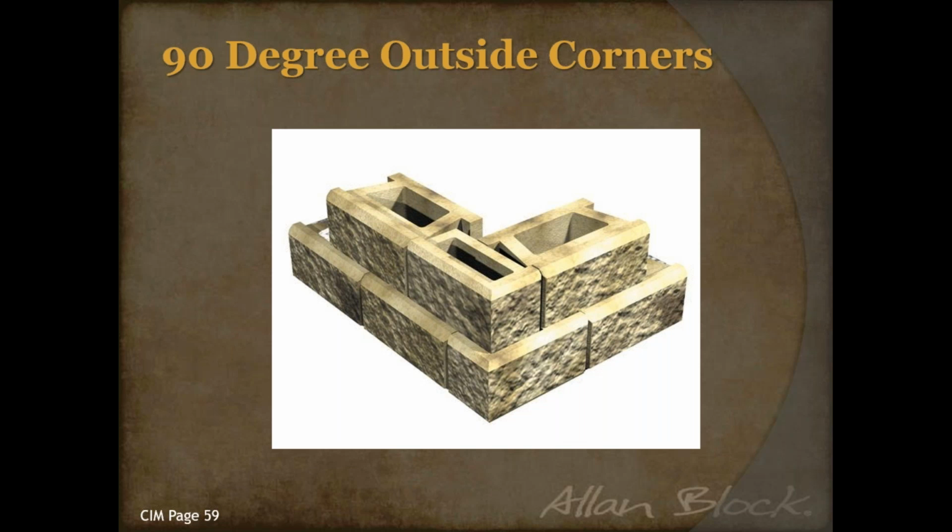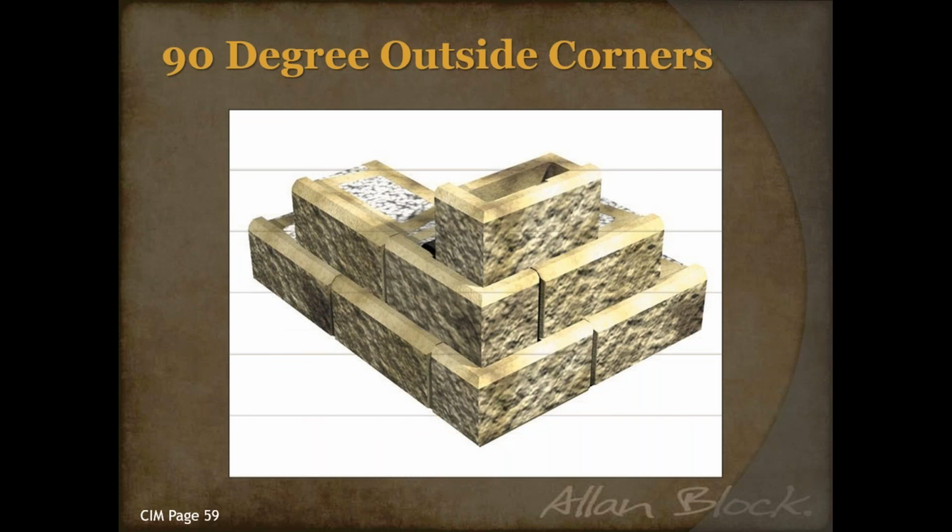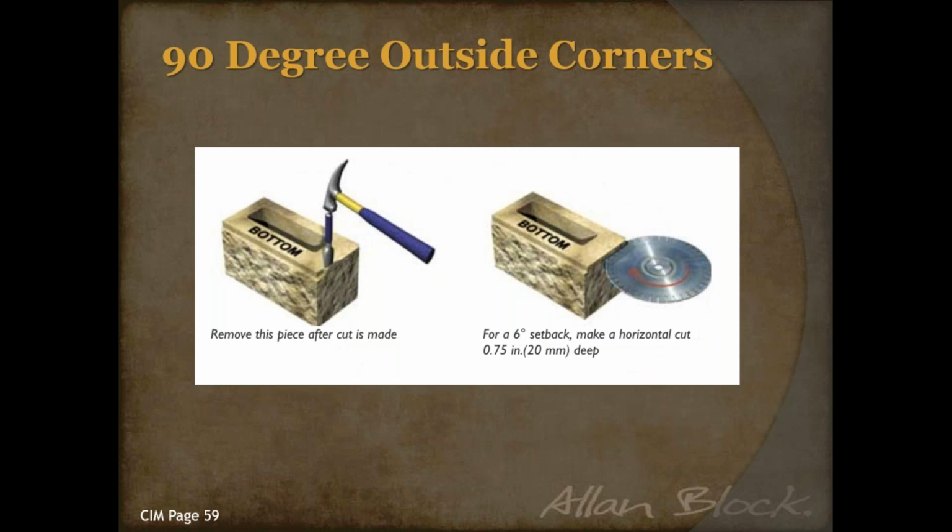But like I said, with corners, you're just going to stagger that. As most of you guys know, laying your base, it is much easier to do a step up than a step down. So try to find your lowest point possible when you lay that base course and work from there. But once you've got your base course in, I would suggest you try to find your corner. Start your next courses at your corner. That way you can use full-size block and not have to make that cut right at the corner, and that might eliminate some of the headaches you have dealing with the corner. So again, always start your base at the lowest point if at all possible, and then for your following courses, start at that corner and work away if at all possible as well.